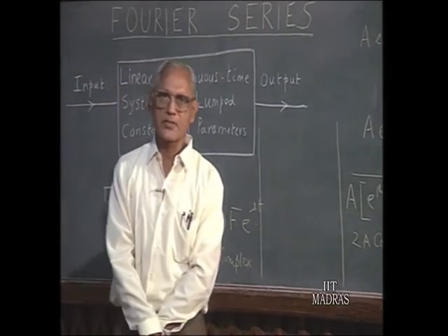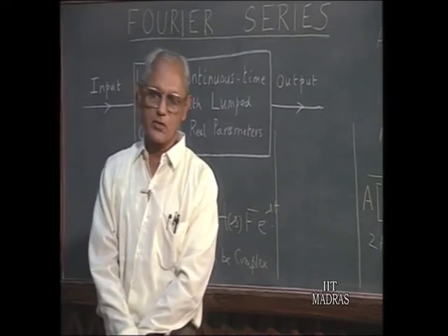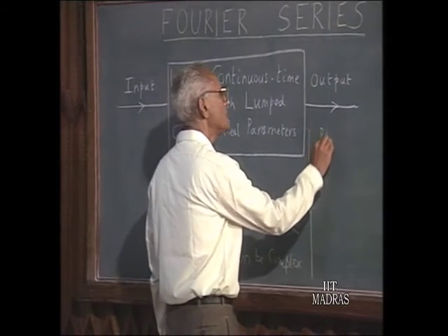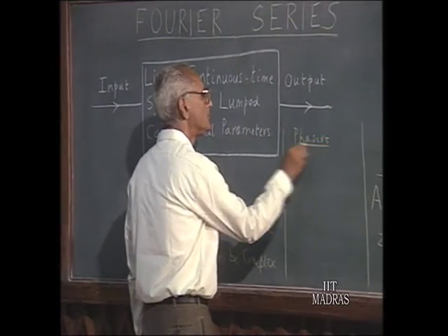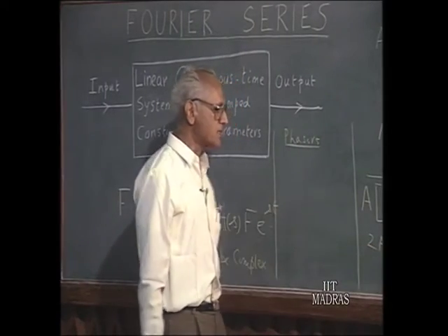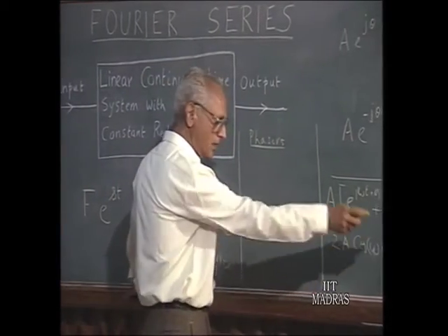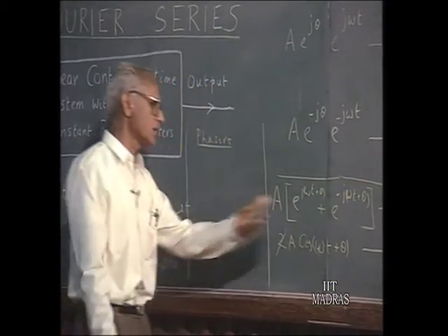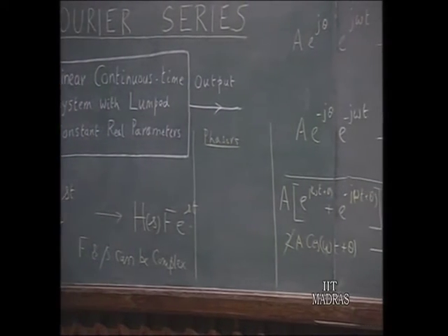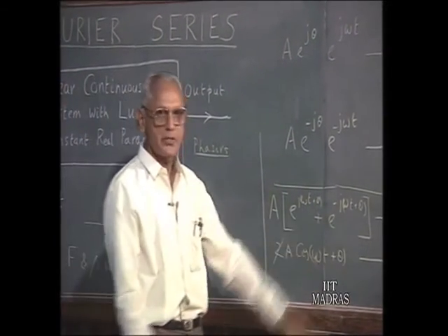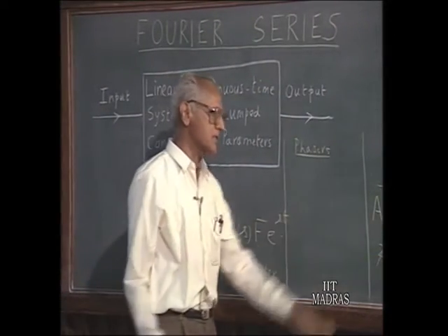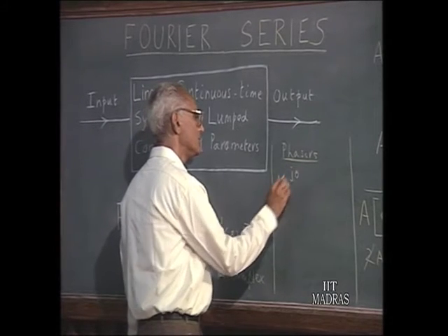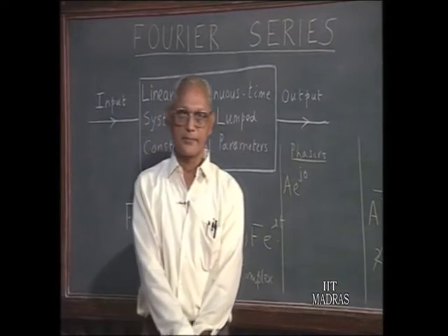Normally, when we deal with sinusoidal functions of time in AC circuit analysis, we use the phasors. Let us see how these are related to the phasors. In terms of phasors, we express this. For example, now that we have got this expression, I can drop this 2 here and this 2 here and simply deal with a cos(omega t plus theta). Because after all, if this is reduced by factor 2, output also will be reduced by factor 2. The phasor for this, as you recall, will be written as a e to the power of j theta, a at an angle theta.